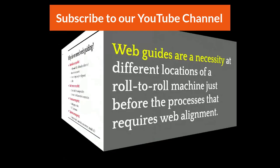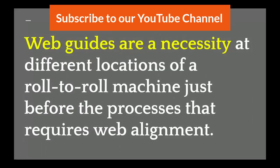So web guides are necessary at different locations of the machine because you might need alignment at different parts of the machine. That's the main thing with web guiding. You have to put a web guide in front of any process that requires web alignment.